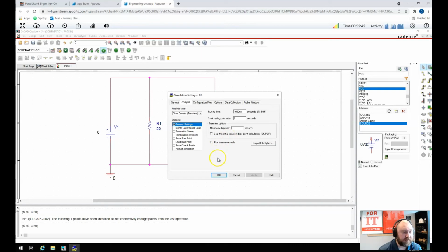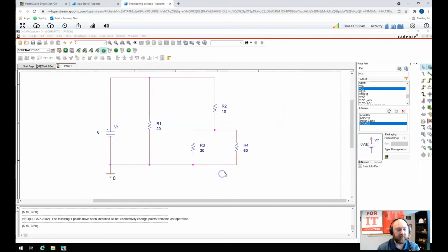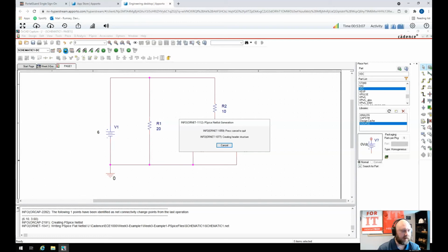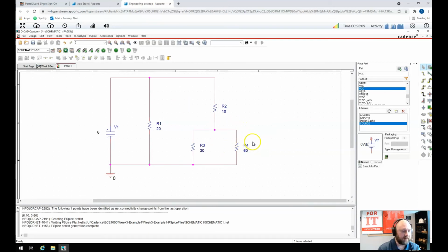So there are lots of different settings, but right now when you're doing a DC simulation, which is what we're doing, there's nothing to do, and we click on OK. Now we're ready to run the simulation. I'm just turning something off that was already on there. Depending on how your simulator is set up, if you have any of these V, I, or W's highlighted, once we simulate it, it will run here and show you those. But I'm going to click on the run profile, and it created a little information there. Now we get to play the waiting game again.